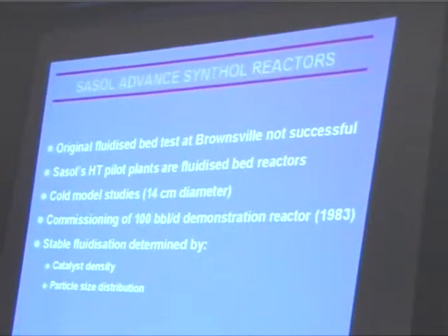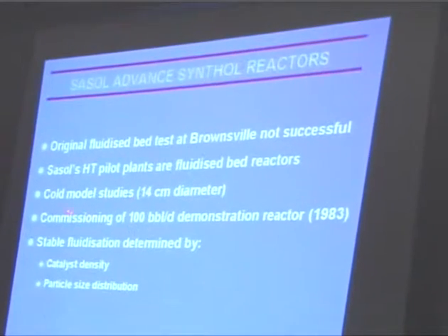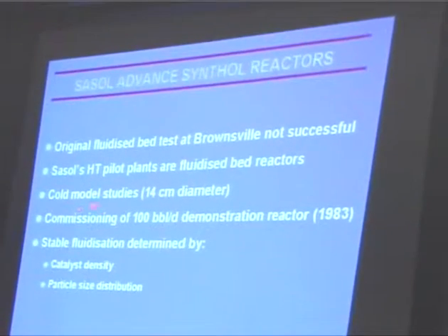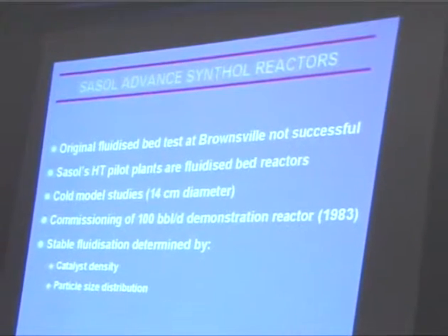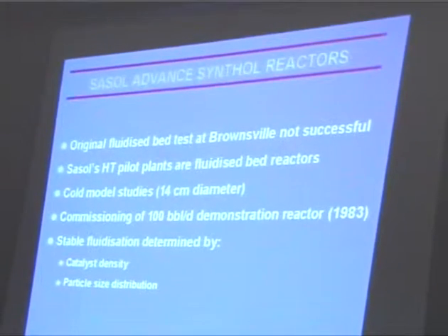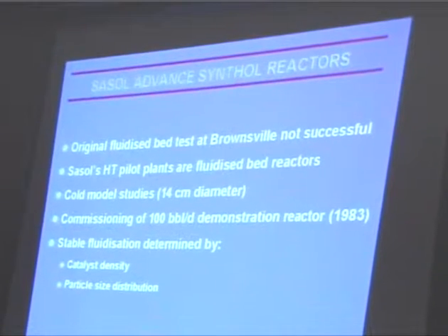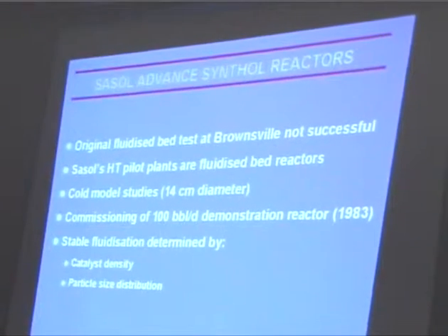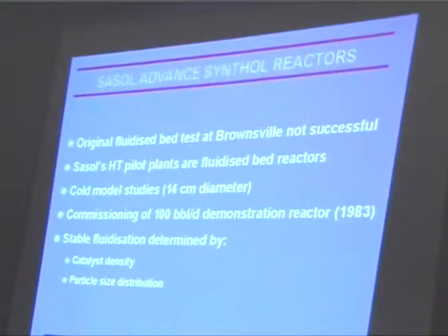So we know how to produce a catalyst. We have looked at the fluidization properties in cold models. Now was the time to do this fluidization on a larger scale. Cold models for FT are not really sufficient because you form carbon with iron at those temperatures, so your catalyst density is changing continuously. Your particle size is also changing, but not to the same extent as your density. So you have to do these studies at realistic operating conditions. So you need a reactor like that, otherwise you will not be able to design a commercial sized fluidized bed reactor.